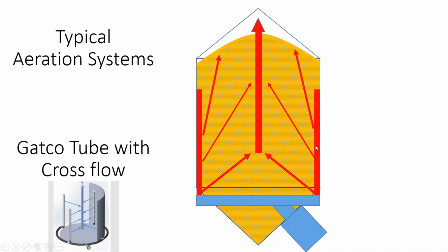So as air is injected into these, it's going to want to flow preferentially horizontal, and because you've got this easy exit, it actually will stick to that horizontal flow path. And the idea again is that you will get less back pressure, and you will get your moisture out of the bin quicker.